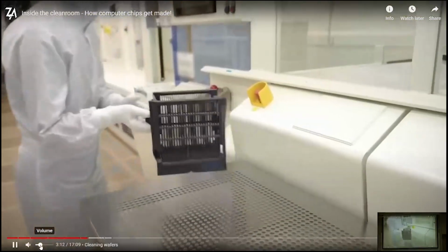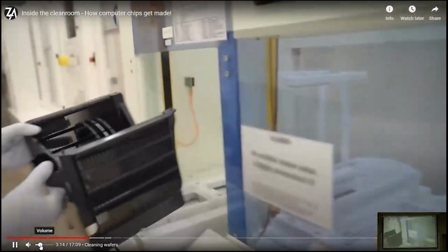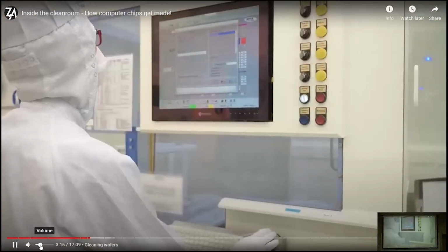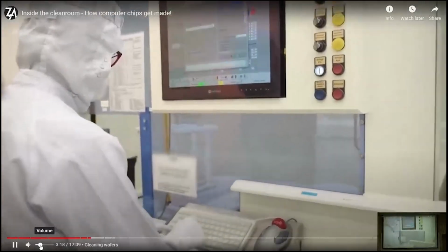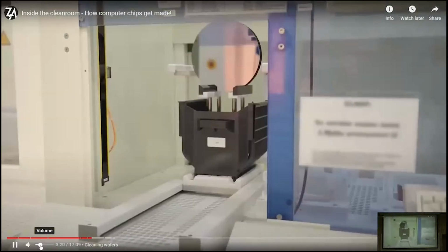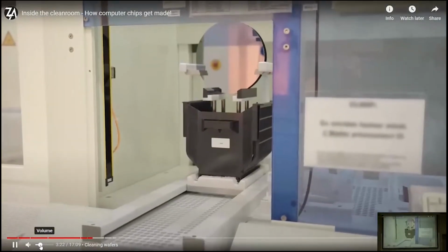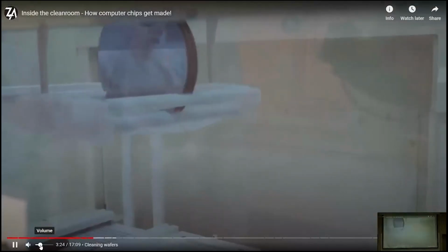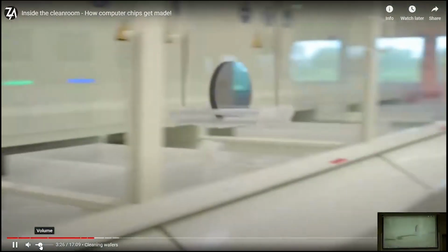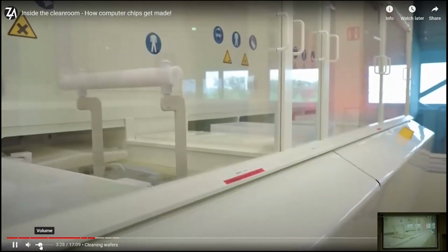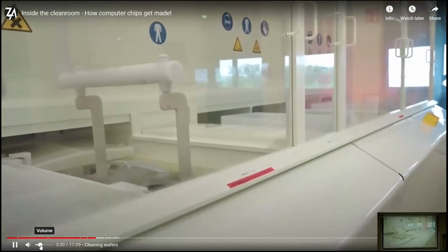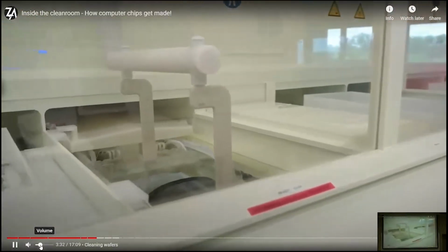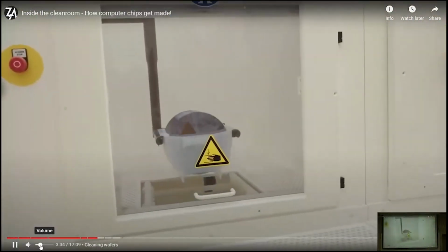The first thing is that they clean the wafer. So they use different chemicals, for example, to clean it from organics, from oxides, from particles. So a batch of wafers containing 24 wafers is immersed in an etch bath. In the cleaning and wet etching section, they have 14 different tools from 9 manufacturers. These tools can handle whole boxes of wafers at once, or just work on a single wafer.